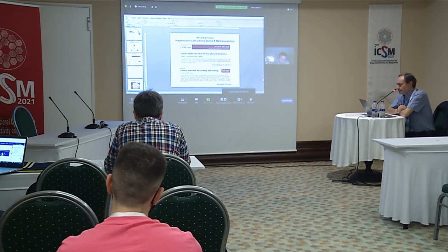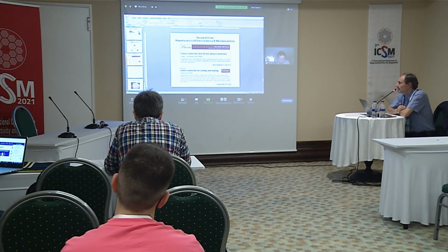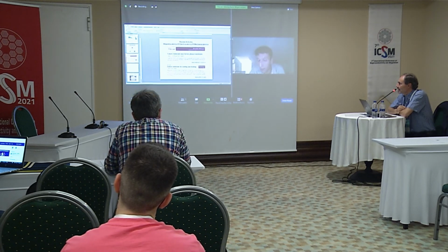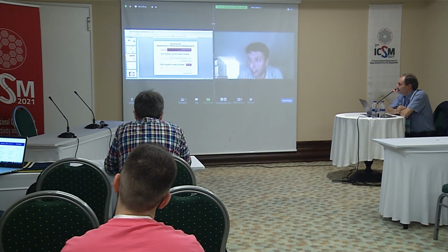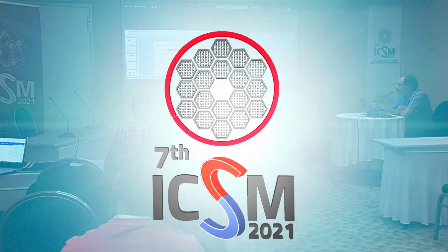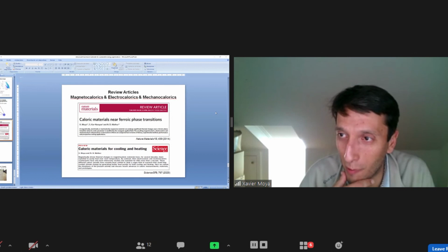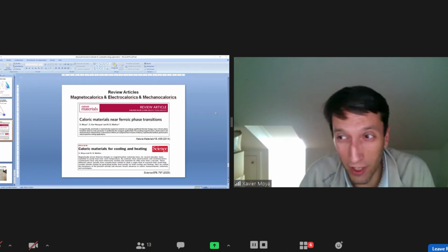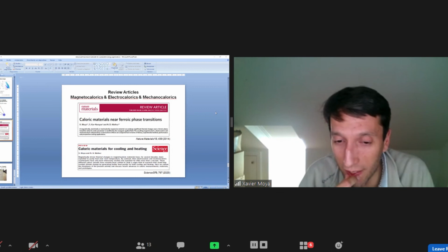Yes, they are similar and different in a way, because with thermoelectrics you can actually get cooling and heating, and you can also harvest energy, right? These caloric materials can also be used for cooling and heating or for energy harvesting. But I think they are complementary in the sense that in thermoelectrics, you don't drive a transition, you just use the fact that electrons and holes can carry heat with them, so you can use them for pumping heat. In these caloric materials, you exploit a phase transition, so it's a different phenomenon.